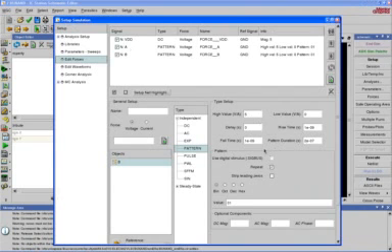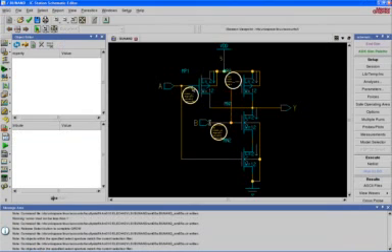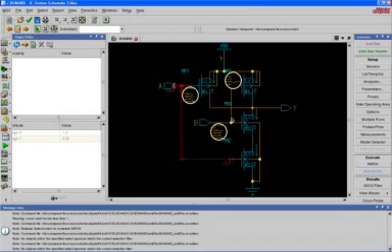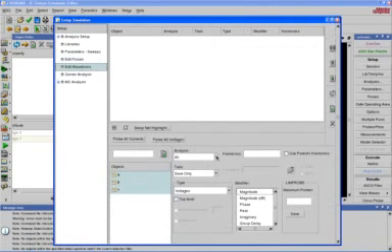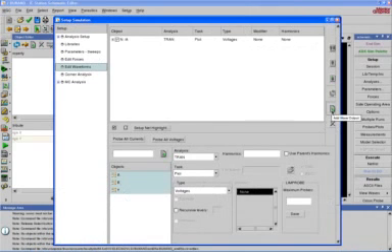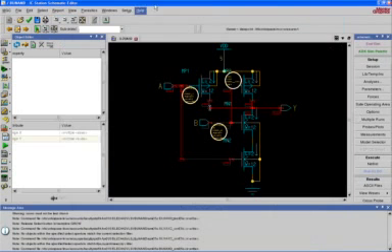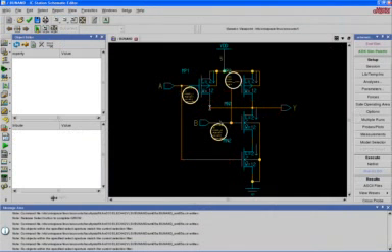Okay, now let's set up so that we can actually view the waveforms for A, B, and Y. So click on A while holding the control key on your keypad, highlight B and highlight the wire for Y. Now go back to setup simulation, click on edit waveforms. All three should be highlighted. Under analysis, scroll to transition. Under task, plot, and everything is all set. Click on the plus. So we've set up our waveforms. So far we have the waveform inputs set up. We set it up so that we can view the waveform.